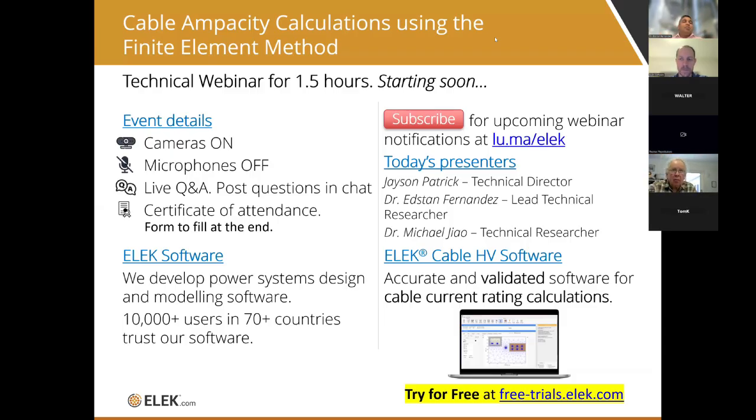So now the topic FEM, a very hot topic these days. Always IEC has been used. IEC 60287 has been a standard which was used as a benchmark for quite a lot of years. Then came TB 880, which again benchmarked many of the calculations of IEC. But the problem with IEC was that it's always limited to certain things, for example, a single backfill, no complex convection scenarios. So all these shortfalls of IEC, we will be discussing today.